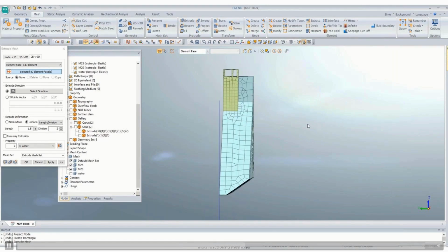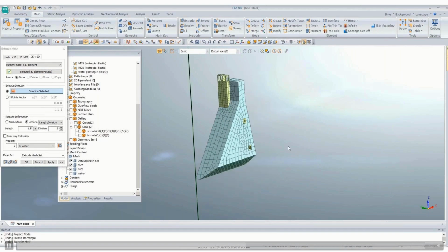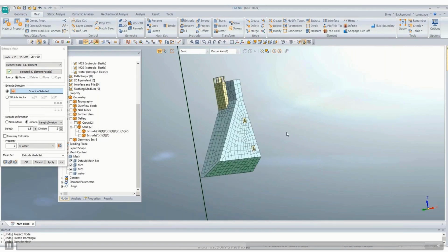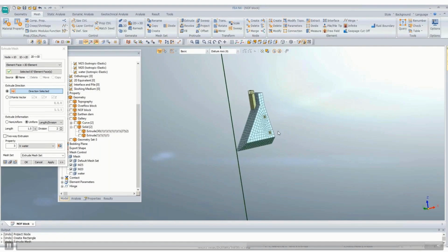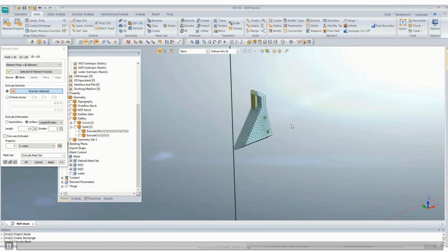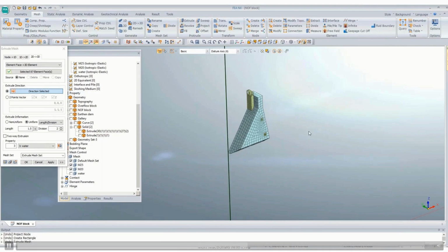Okay, and direction is vertical. So I'll be modeling about 100 meters in vertical direction and on each side of the dam. In one of the examples in the USACE Engineering Manual, they have also modeled the depth equivalent to the height of the dam, and on either side also almost equal to that.